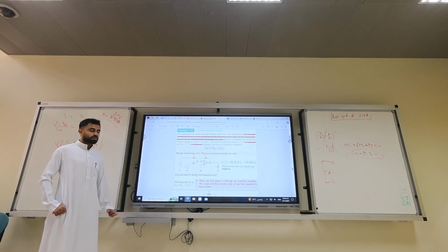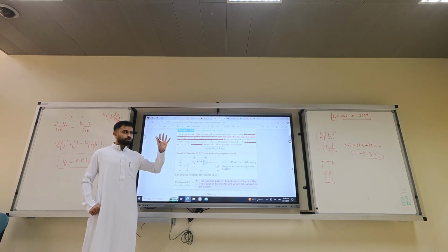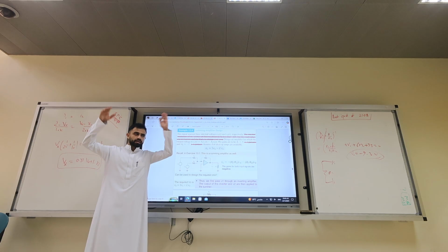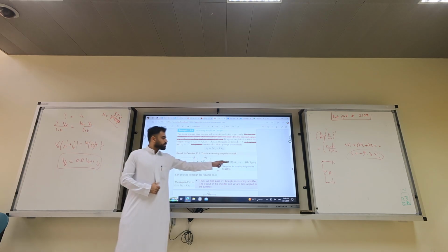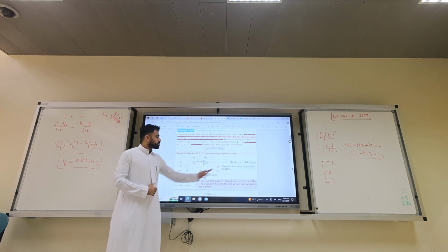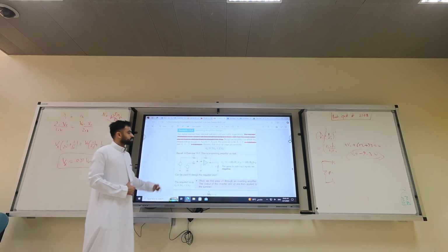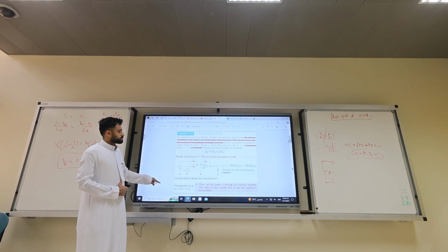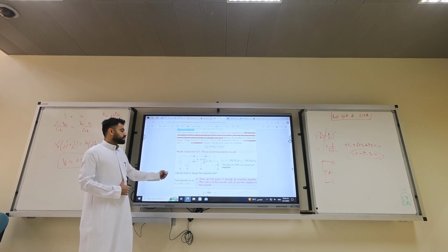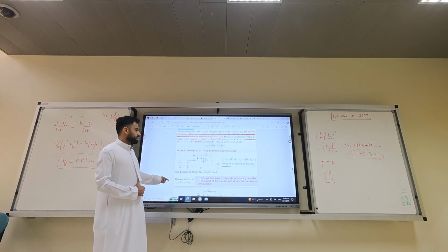Get it? Let me repeat. To get the 5, we want to have between 100 ohm to 1 meg. So let's pick kilo. So RF is 10 kilo. 10 kilo over 2 kilo, you get 5. And 10 kilo over 5 kilo, you get 2. Okay? We first pass V1 through an inverting amplifier, and the output of this inverter and V2 are then applied to this one.